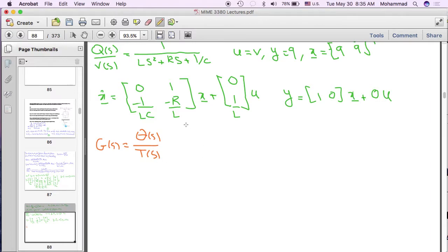And if you remember, the basic equation was Newton's second law in angular form, or in rotary form, and that essentially says J theta double dot is equal to all the moments, and the first one is minus B theta dot. The second one is the applied moment or applied torque that causes the motion, and the last one is from, let's draw the free body diagram.